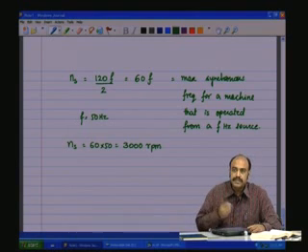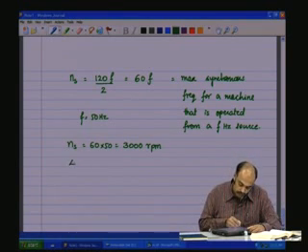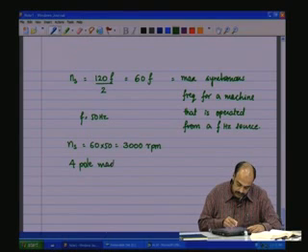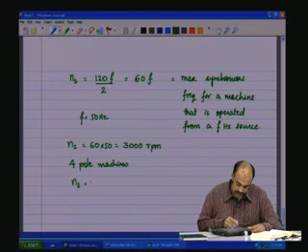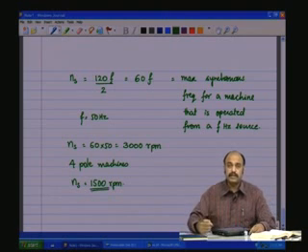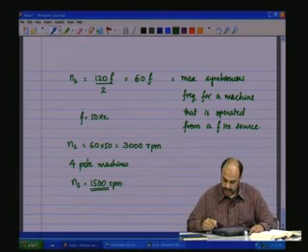And many of the machines which are there in the market are 4-pole machines, which means the Ns typically of all these 4-pole machines in our country, you will see they are 1500 RPM, which will be on the nameplate. So keep that in mind.